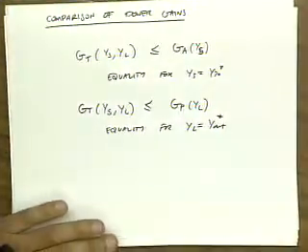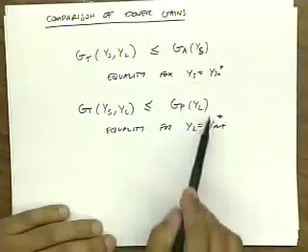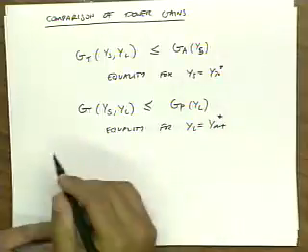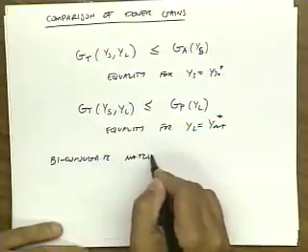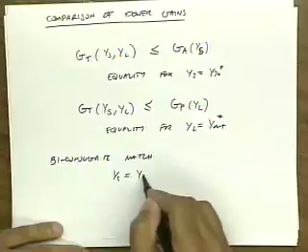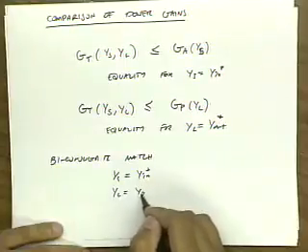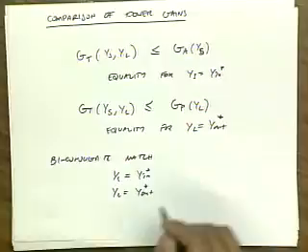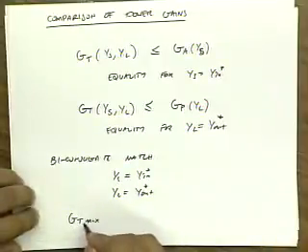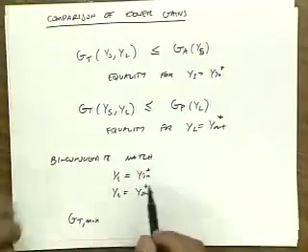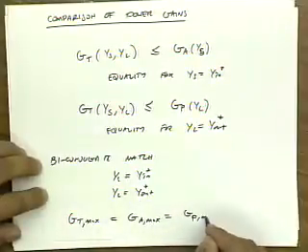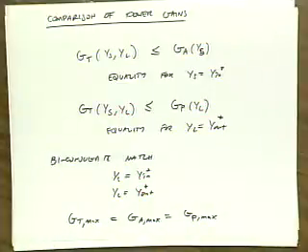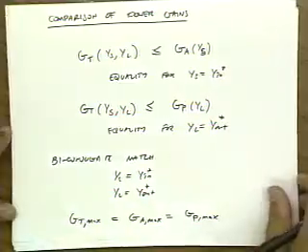So it's now pretty clear that if we simultaneously match the input and output by conjugate match, then GT max, the maximum obtainable gain as a function of the source and load, is equal to GA max, and it's equal to GP max. Okay? So our intuition is right.